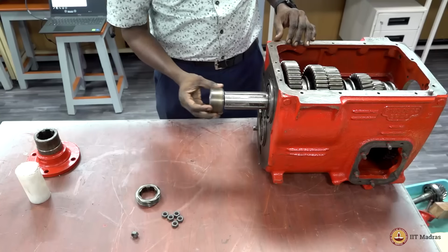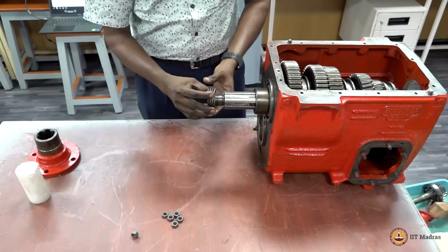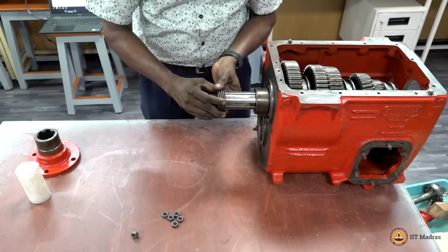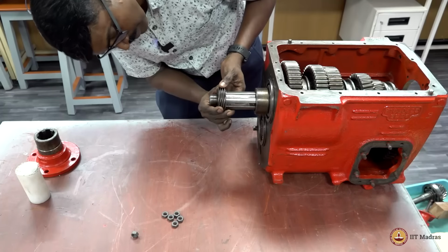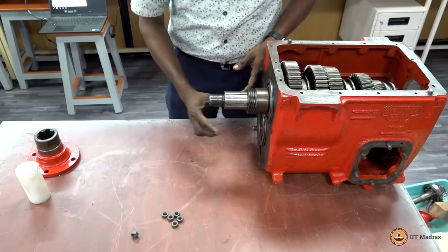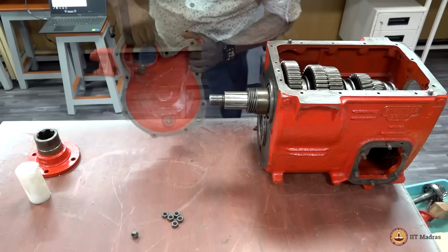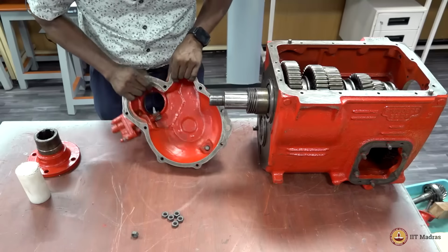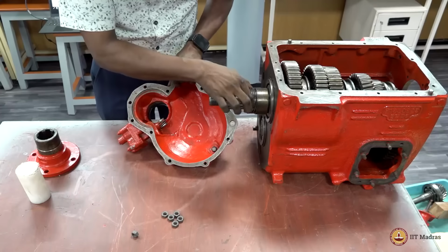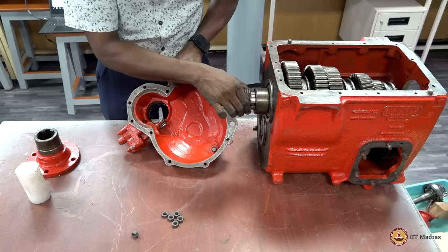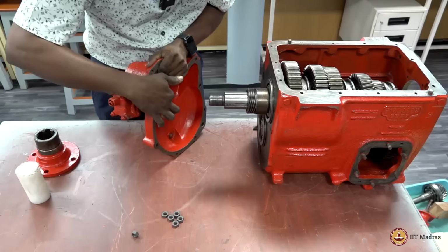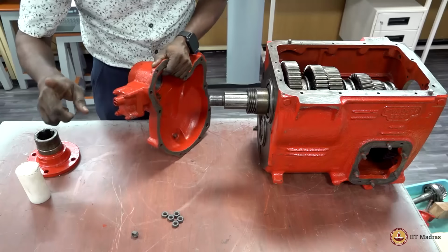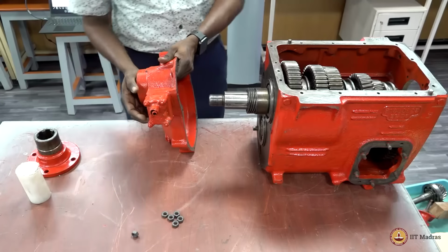Then the distance piece, with the skew gear for speedometer purposes. Now the rear casing. On the rear casing, you can find a pinion that meshes with the speedometer skew gear. Then through this gear transmission, the drive of the gear will be transmitted through a cable to the speedometer to read the vehicle longitudinal speed.